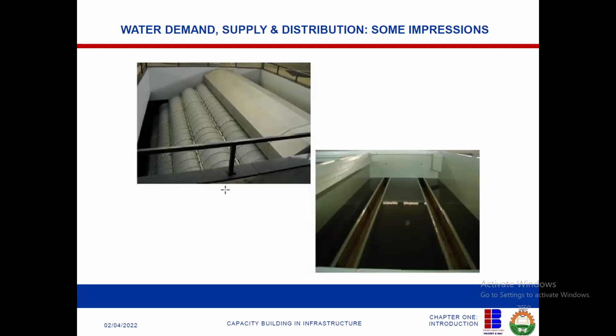So that's why most times when you look at surface water, it is turbid, brownish and what have you. But as soon as you aerate it, you see it percolating. Once it gets the oxygen, it becomes massive, sort of, and then it settles. So it's either you flush it through a bottom outlet, or you further put in coagulants. When you put in those coagulants, they flocculate, and when they flocculate, you can easily filter them.